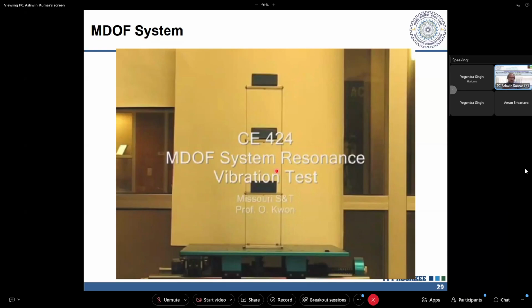We have a homogeneous part and a particular solution part, and we combine them to produce our final solution. Again, we are interested in the displacement time history, and in that also in the peak value. One thing I said: in a forced vibration there is a transient phase and a steady state phase. The steady state remains as long as the machine or forcing vibration is present, whereas the transient phase is like a free vibration analysis. If it is set into motion and damping is there, it will die down and only the steady state will remain. If your external forcing function is not P of t but a ground motion, then I said it is not easy to use the classical particular plus homogeneous solution to find the solution to the equation of motion.